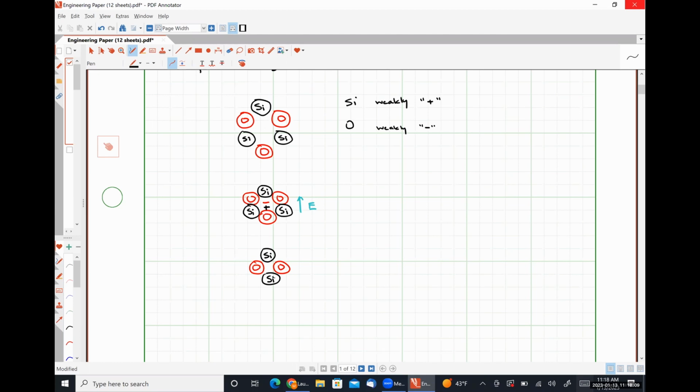And so that trigger is a spring that's storing energy, and then once you pull it down far enough, a hammer releases and strikes a piezoelectric crystal. And that piezoelectric crystal has leads that run up the length of the barrel of your lighter. And concentric to those leads is a gas line. So when you strike that crystal with that hammer, it generates a voltage or an electric field across the distance of those two leads, which in turn creates a spark. And when that spark is in the presence of a combustible fuel, you get fire at the end of it.